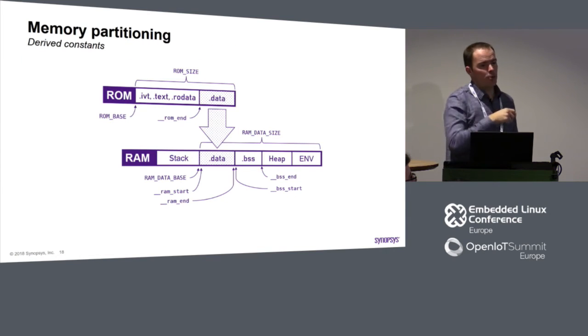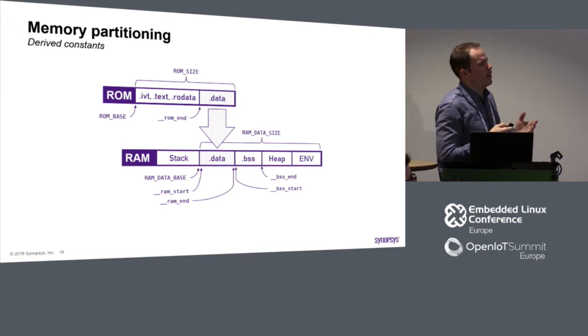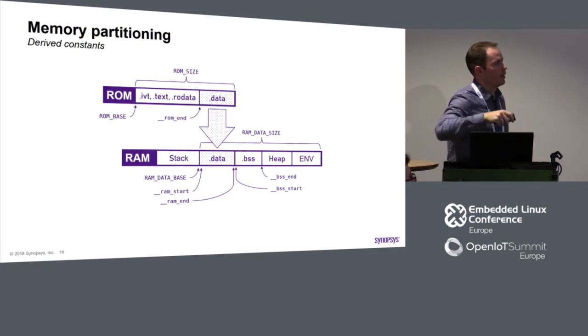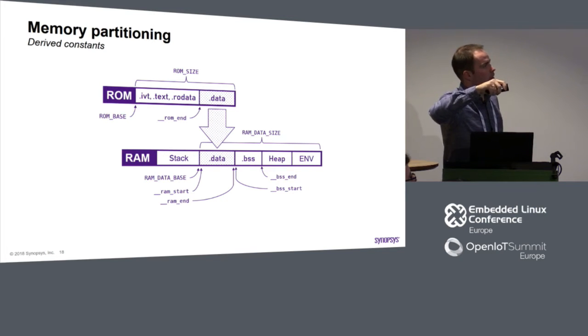And that's what we have in memory layout if we use variables or constants we define by the linker. You see, this is ROM-based, so this is quite clear. It was text-based before. This is ROM end, and this is important because that's the real address where data exists before copy.